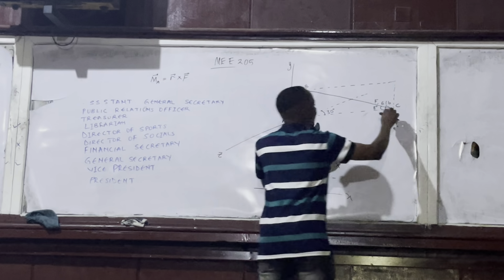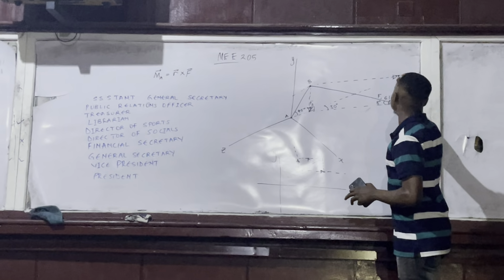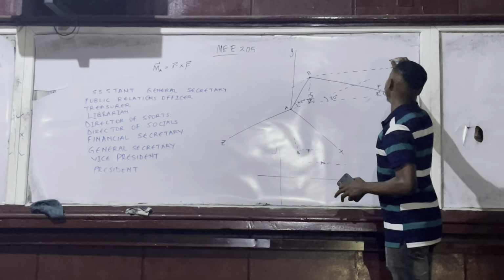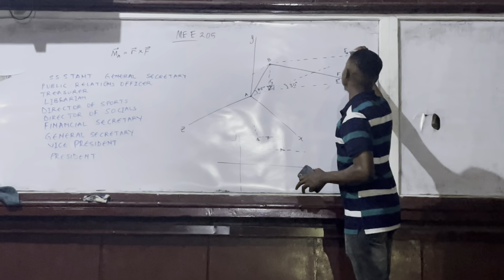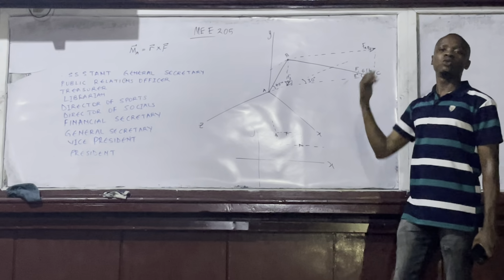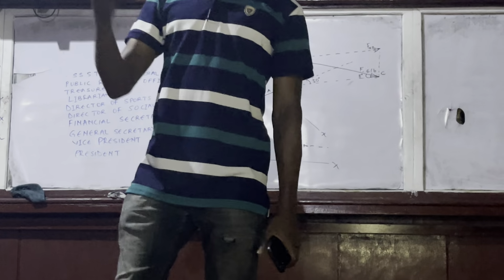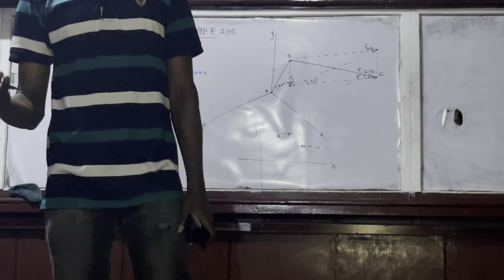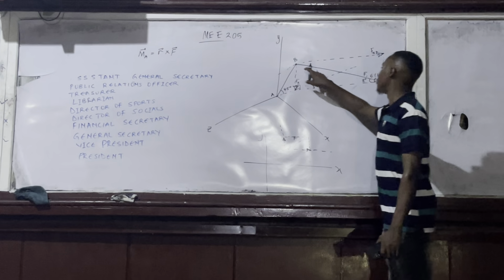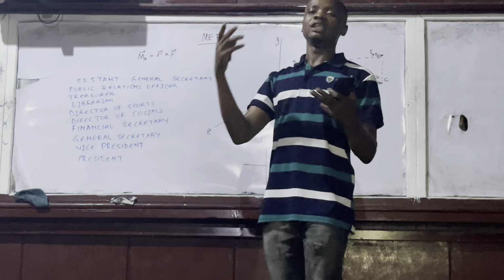Then, when you project this one up here, you are going to have the component that is perpendicular to this one. Is it making sense? That component can be called Fxz because it lies in the xz plane. How do I know it is in the xz plane? Because it is perpendicular to the y-axis. Is this very clear? Yeah. So, we have successfully resolved the force into two components along or in its plane.